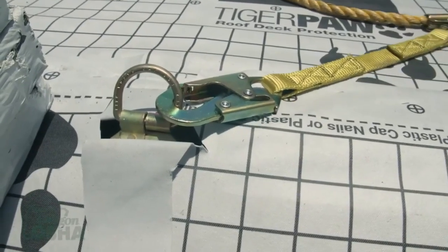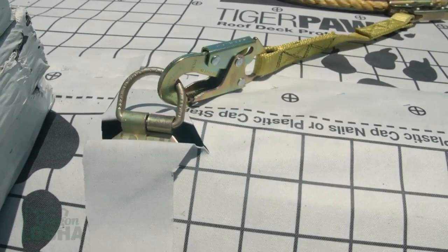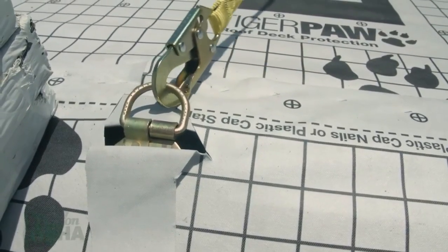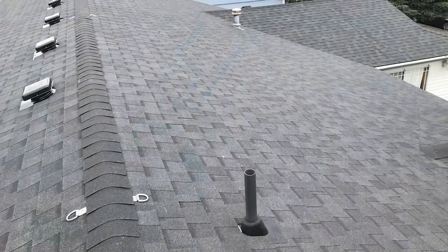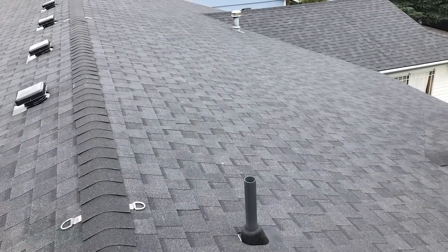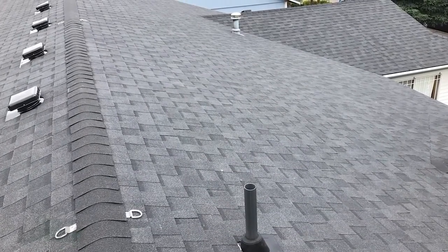Another type of anchor that I wanted to talk about was the permanent anchors. You can find these anchors for about $20 to $25, and the idea is they go underneath the ridge cap on a roof. As your roofers are going up, they put this anchor in place and then cover it over with the roof cap, and that anchor stays there for the life of the roof. So if anybody, including the homeowner, has to get up on the roof, they already have something set in place to tie off to.